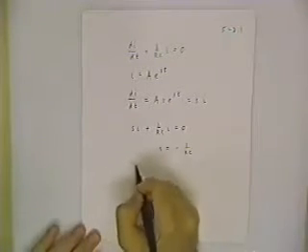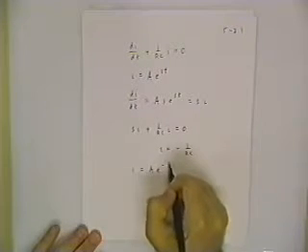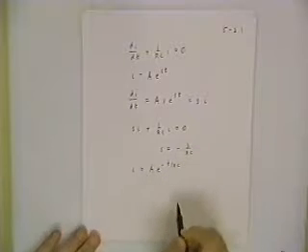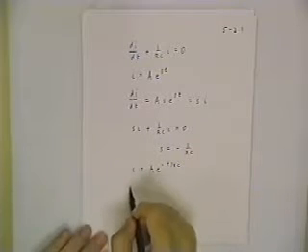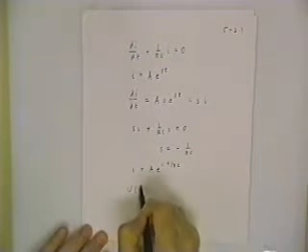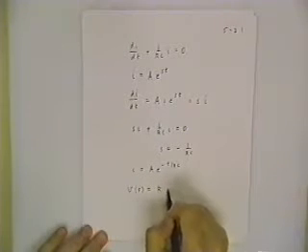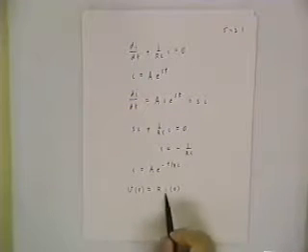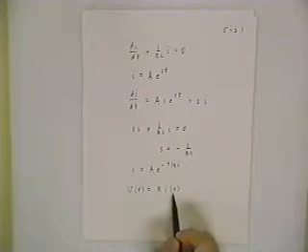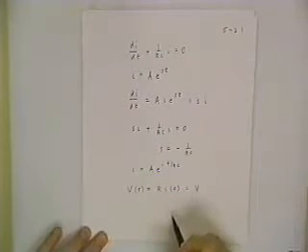What we can do now is come back to the equation I of t equals A e to the minus t over RC. Now all we have to do is figure out what this constant A is. And we can get that from the initial voltage. V of 0 is equal to the resistance times I of 0, and we know that because the voltage on the capacitor is the same as the voltage on the resistor. They happen to be in parallel. And this is, in turn, V volts.